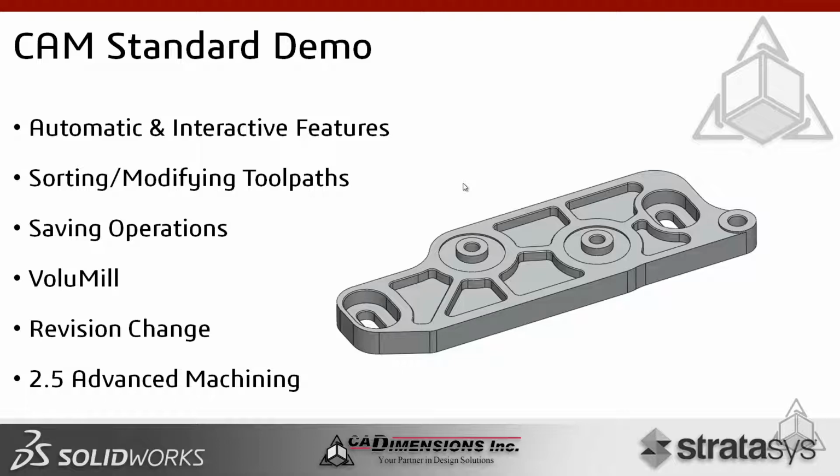Now, sorting the actual toolpaths, CAMWorks or SolidWorks CAM has a sorting operations where you can quickly sort by different parameters. Like you can do all of your roughings before your finishes, all your center drills before your drills, and you can also combine operations together that utilize the same tool so that you're not frequently changing the tool. So there are a lot of these things built in that are very, very quick. Saving the operations, I showed you how to save back to that database. I didn't show you how that would work if you were to automatically run that through feature recognition again, but you guys do have the software, so you can definitely take a look at that.